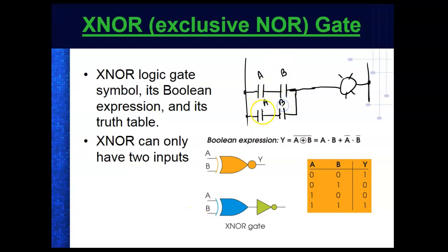Okay guys, so this is what we do. I'm not drawing the control. I know we've got two controls, A and B, but I don't have the button pressed, so they're both false, and the output would be true. If I press A, then this contact is going to open and this is going to close.